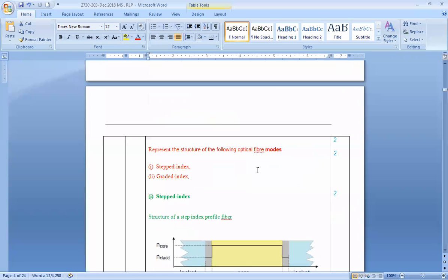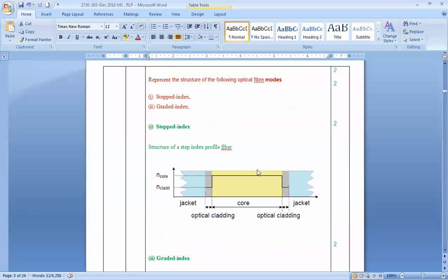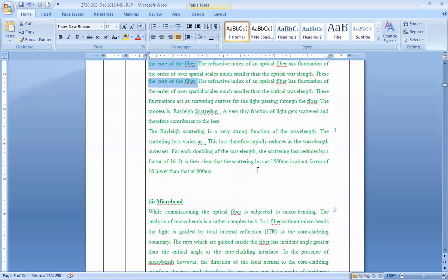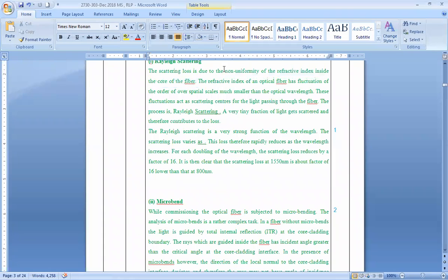If there is no proper reflection of light, then there can be a lot of scattering. This can happen because of the non-uniformity. So maintaining a proper refractive index is important. Now, as I mentioned, what is refractive index? It is the property which helps the light to pass through. Air has 1, and we saw in the previous example glass had 1.5. So the index has changed, and if the index has changed, the way in which light propagates through the optical fiber also changes.